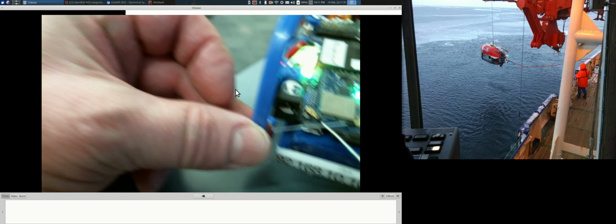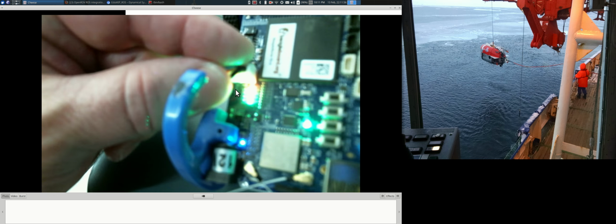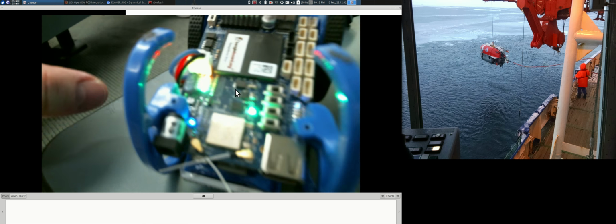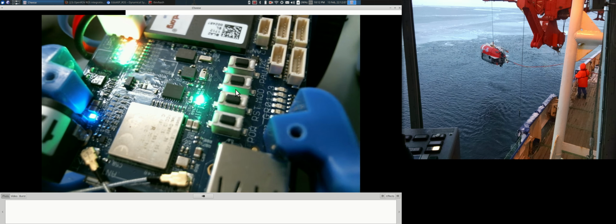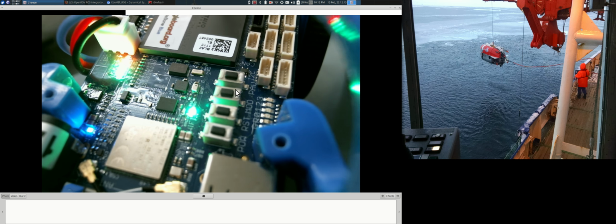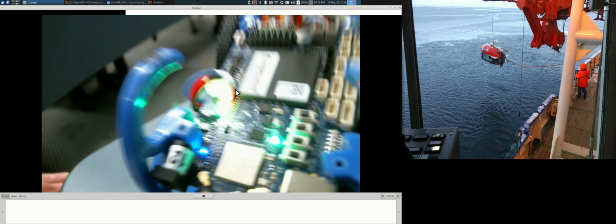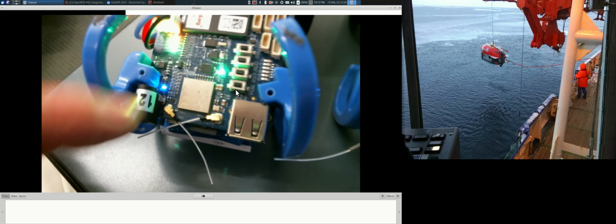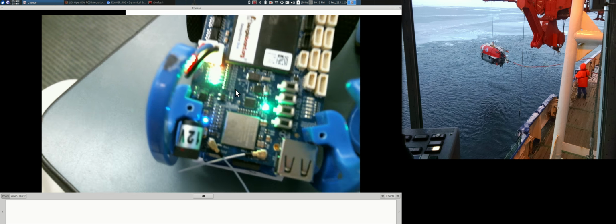For the BeagleBone Blue, there's one 12-volt connection to it for charging, and there's circuitry right here that we're being blinded by that'll charge the lithium polymer battery pack here. One of the really nice things about this is that most embedded boards that you get have some kind of a processor and various sorts of I/O, but then you're like, oh, I need to power this thing. And you have to have this entire separate battery subsystem. Well, in this case, the battery subsystem is built on board. There's 4 user switches that you can use for various things. Right now, if you press the power switch, it's running a little daemon. It'll power down the machine.